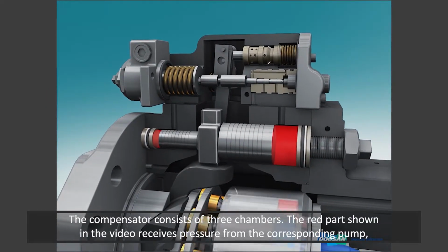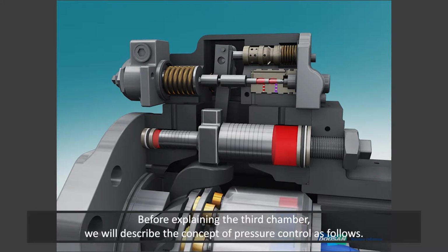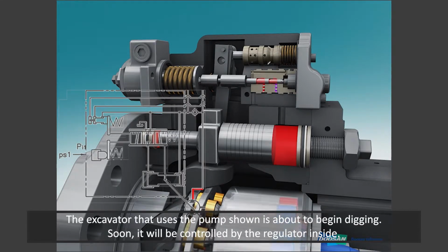The compensator consists of 3 chambers. The red part shown in the video receives pressure from the corresponding pump, while the blue part always receives pressure from the opposite pump. Before explaining the 3rd chamber, we will describe the concept of pressure control as follows. The excavator that uses the pump shown is about to begin digging. Soon, it will be controlled by the regulator inside.